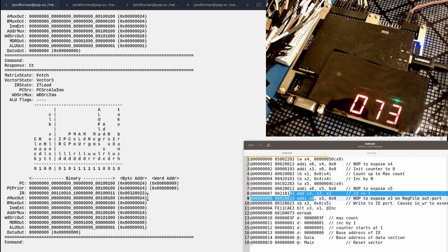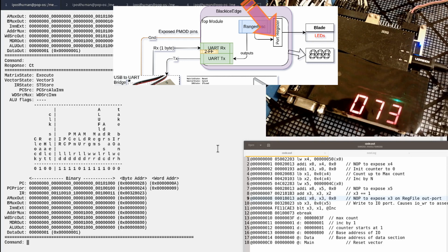And now we're going to move on to this very first instruction. This is an important instruction. We're going to activate the IO write sequence signal. So you'll notice that it's a 0 right now. As soon as we start executing that, we fetched it, but now we're going to decode. It's still high, so we're not writing yet. We're still going, and now we're executing. We just wrote the value that was in that counter out there. We'll go one more, and there it is.